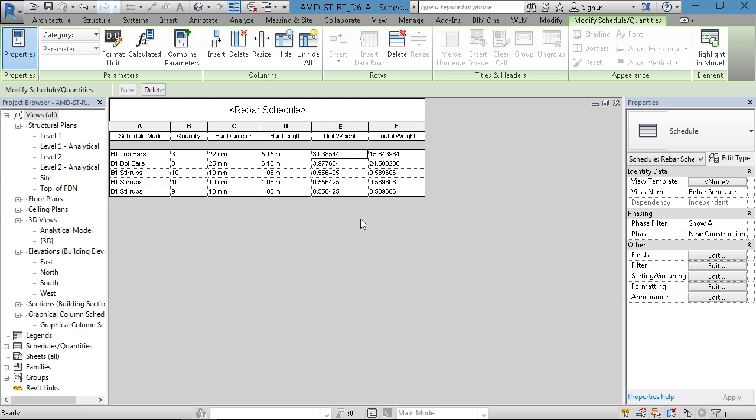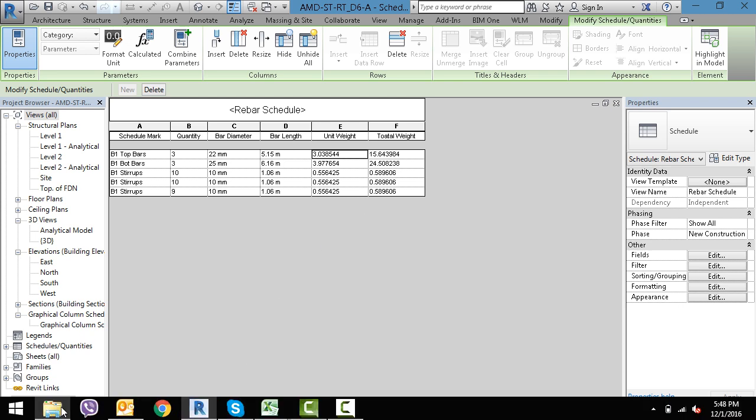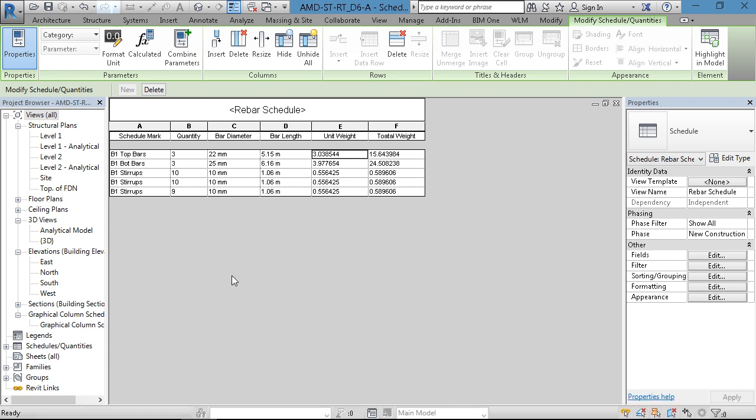Why did you remove the quantity? Yes, that is the total, because we have the bar length and the unit weight of this, so we multiply by this one. But we control the unit, maybe they put mm or 1 meter. So your bar length you need to set to meter.